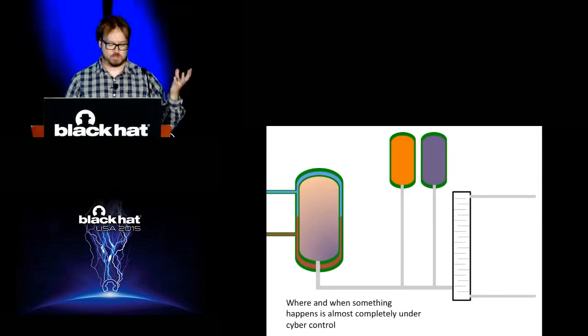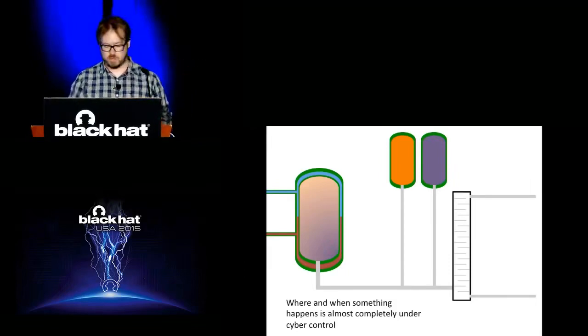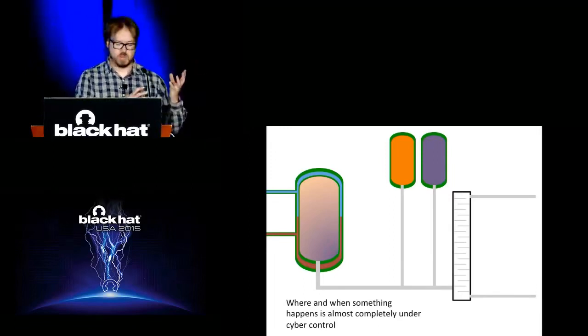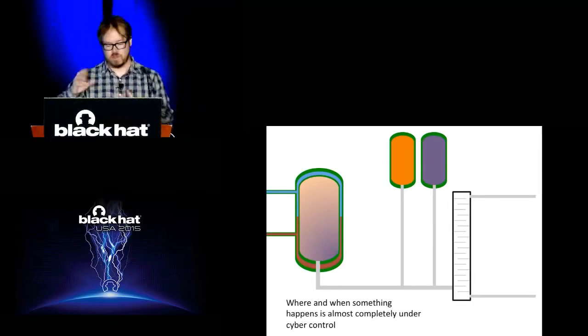If we have a tank and a bunch of valves, switches, and pipes, then when those valves are open and closed are almost always things you have control of once you hack into it. So you can heat stuff up and move it around. This is a pretty common diagram where we have a couple of different tanks in the holding pond, and they're pumped through a common pipe up into the reaction vessel. In this case, we can just reverse that and pump things back into the holding tanks, etc. We can move the unreacted chemicals up into the cracking column off to the left if we don't heat the tank up to its reaction temperature.